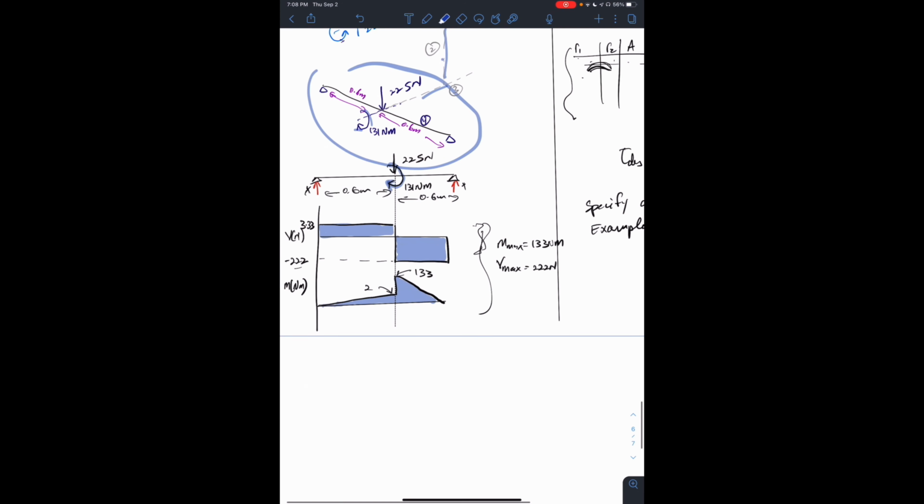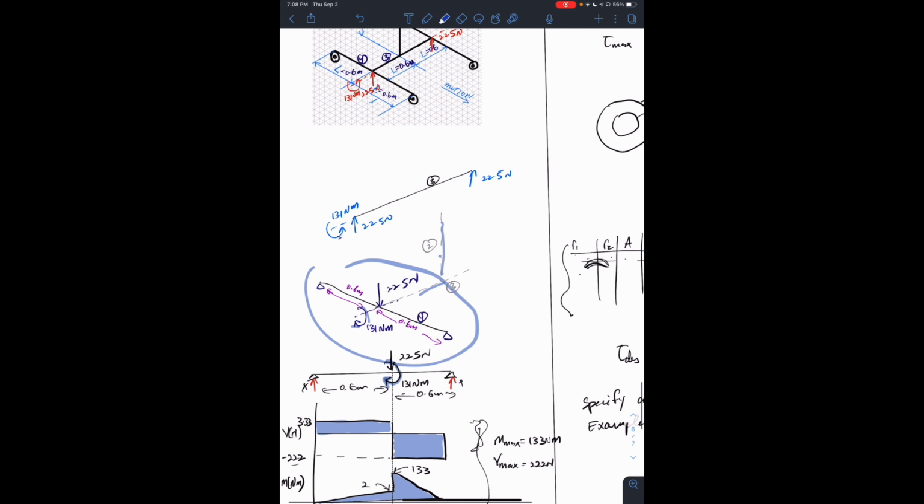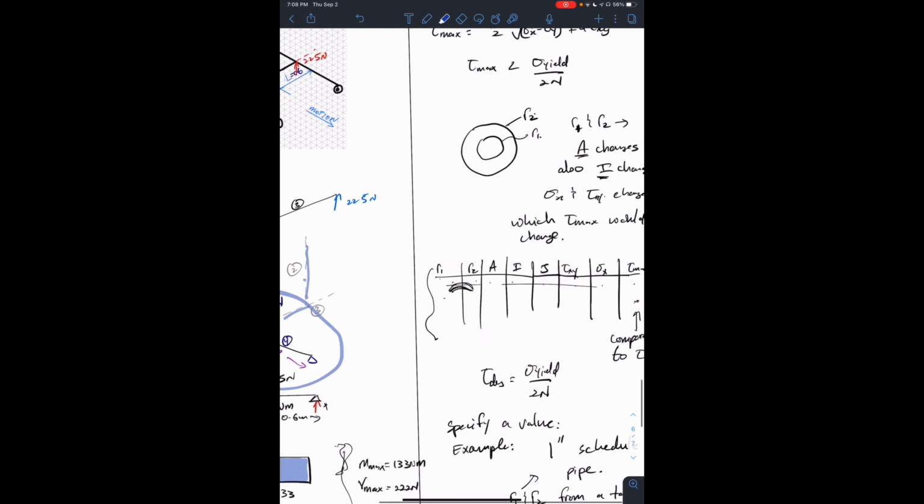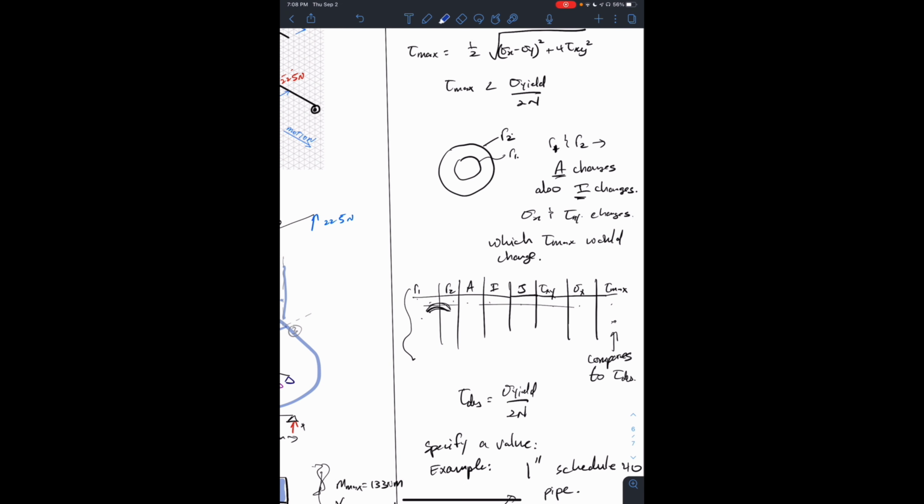The formulas to any shear force and bending moment diagram, that is a repetitive process. And we have seen now with the actual calculations, we could automate in Excel. So you put in the parametric equations once in these cells, you drag it down, and you keep changing your values.